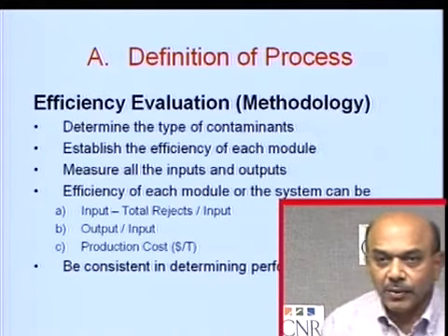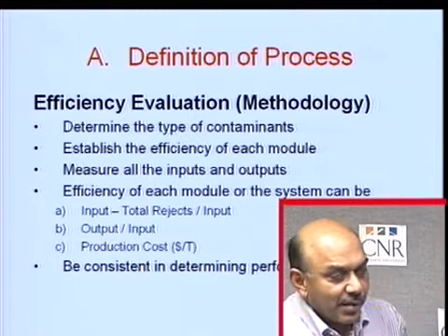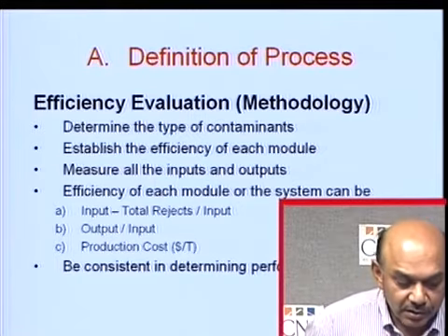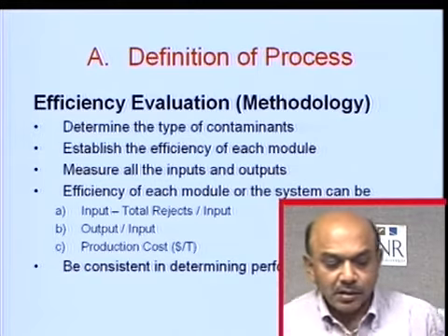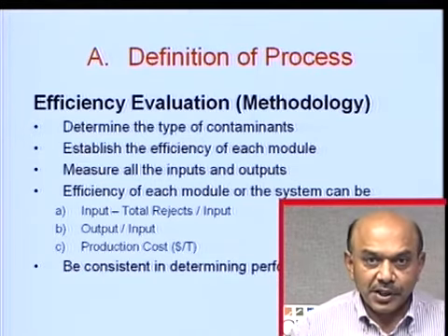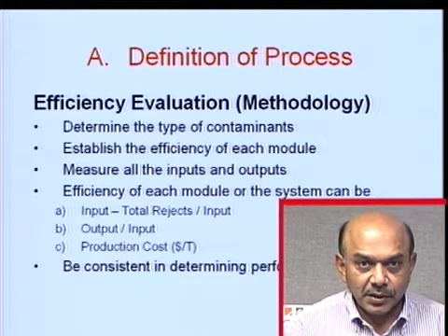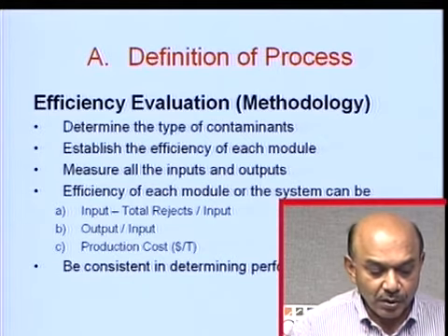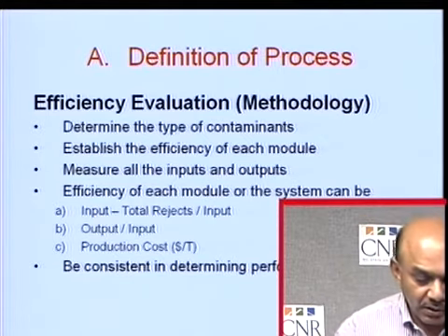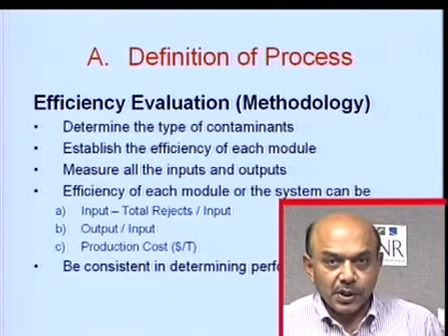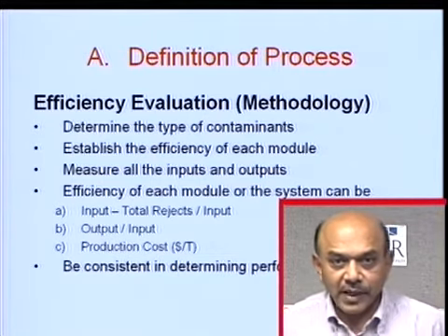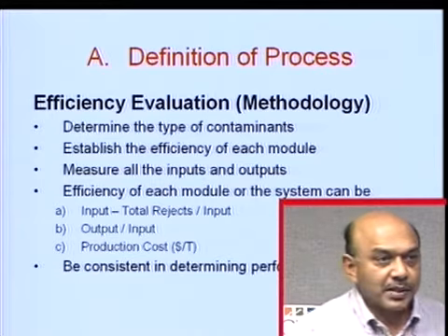And then efficiency evaluation. How do you evaluate the efficiency? That can be done in many different ways in different mills. But you must determine the type of contamination that you have, establish the efficiency of each module, again, I will come back to what is a module, and measure all the inputs and outputs. Once you do that, then you can define the efficiency of each module or the entire system.